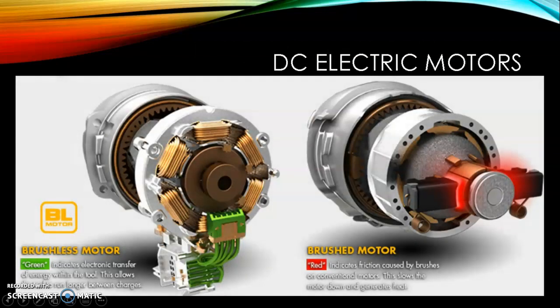Let's start with DC motors. As indicated by the name, it runs on direct current, which allows the rotor to spin inside of the stator. The rotor is a coil of wire which is connected to the electric power supply, and the stator is a permanent magnet or an electromagnet. These motors have the advantage of having more starting torque, faster starting and stopping of the rotation. Side note, which is great for acceleration in electric cars. They are also reversible, and they are capable of varying speeds compared to their AC counterparts. The few disadvantages are that they draw more power to start and require more maintenance throughout their lifetimes.